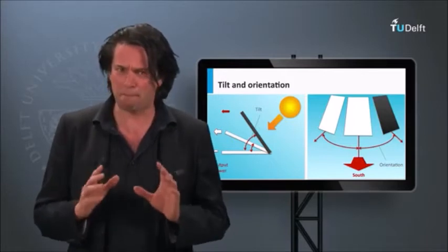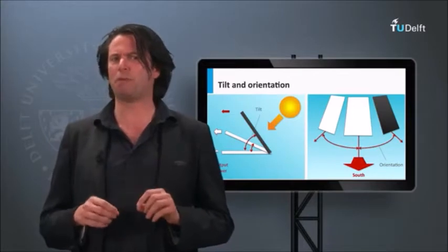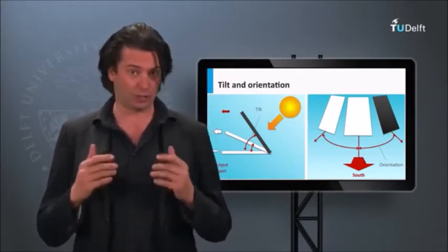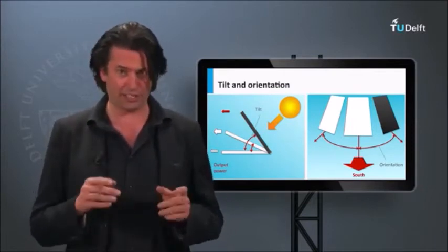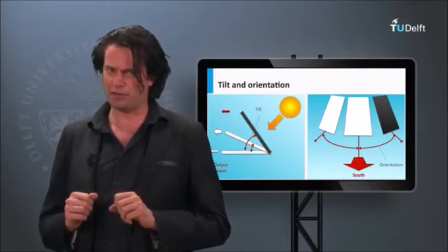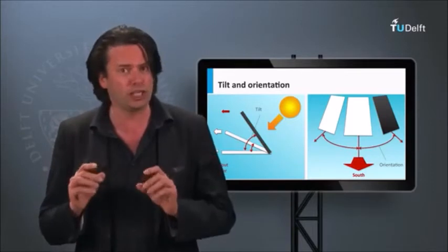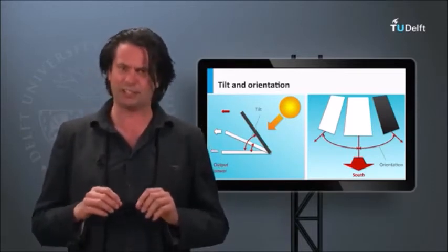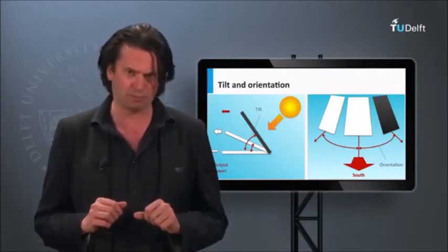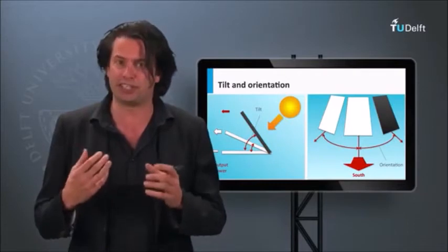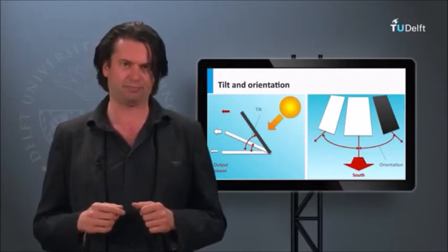It has been seen in practice that optimized angles can give up to 70 to 80% of the maximum PV yield. As long as the solar panels are facing in the right direction in general, that is, facing south for a panel in the northern hemisphere and north for a panel in the southern hemisphere, it's usually observed that the variation in the optimal orientation angle doesn't vary the PV yield much. Consequently, the optimal tilt of the panels helps in saving more energy than the optimal orientation.